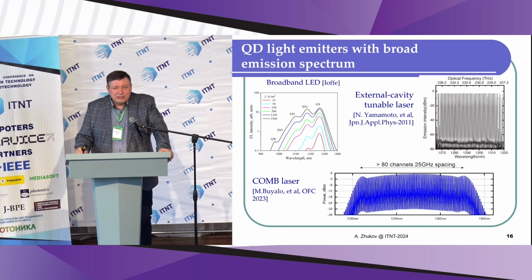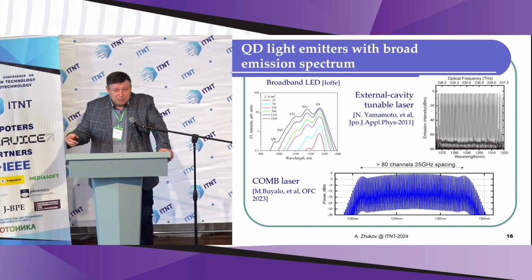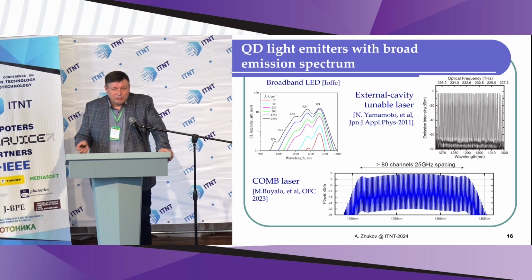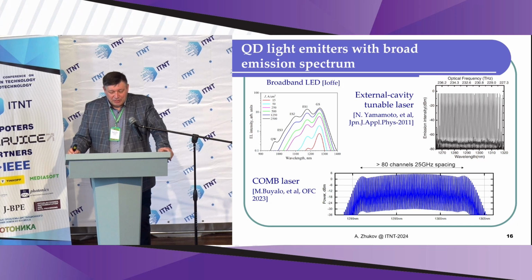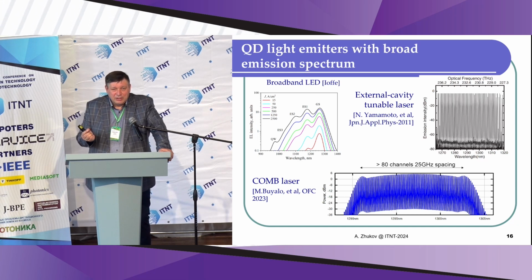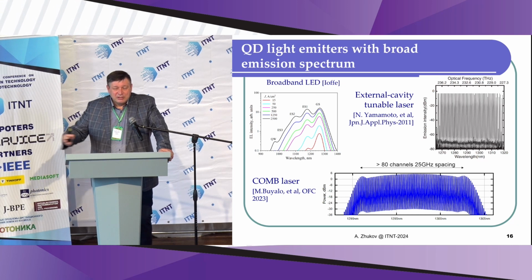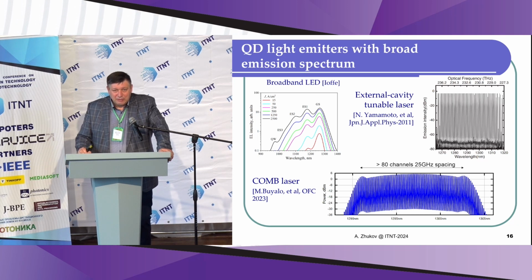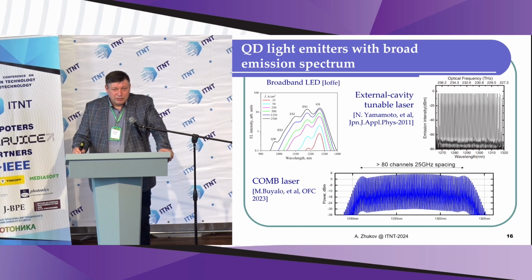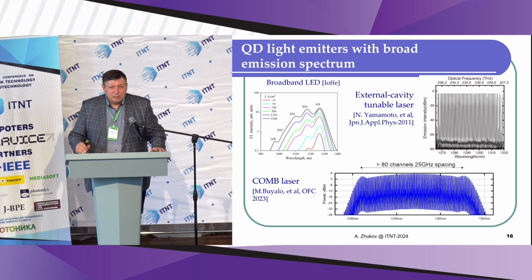Also, I would like to say that typically when people talk about lasers, they want very narrow emission lines, as narrow as possible. But sometimes a broad emission spectrum is required. For example, it is required for a tunable laser, because it's very convenient to have one diode which is capable of providing wavelengths that can be intentionally changed over a very broad range. So quantum dots, because of some distribution of their size, can provide a broad gain spectrum.